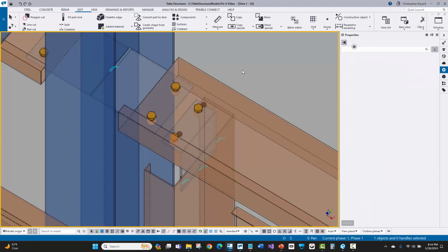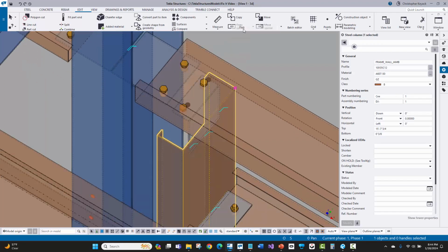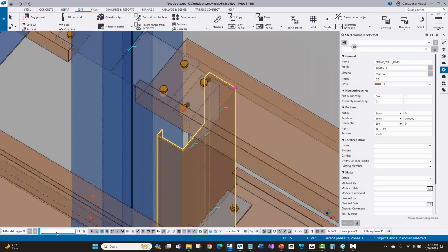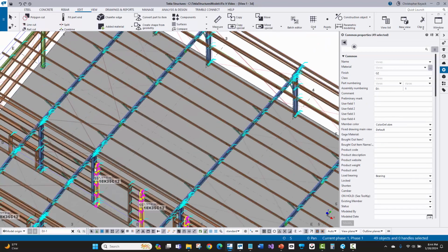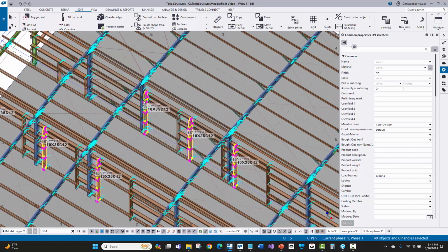And so what I'll do is first find out what this piece mark is, because I'm sure there's probably a few of these across the job. So DJ1 is the assembly mark. Let me do a search for that in the lower left-hand corner, DJ-1, and search, and there are a few of these. It looks like there's 7 of them throughout the model.